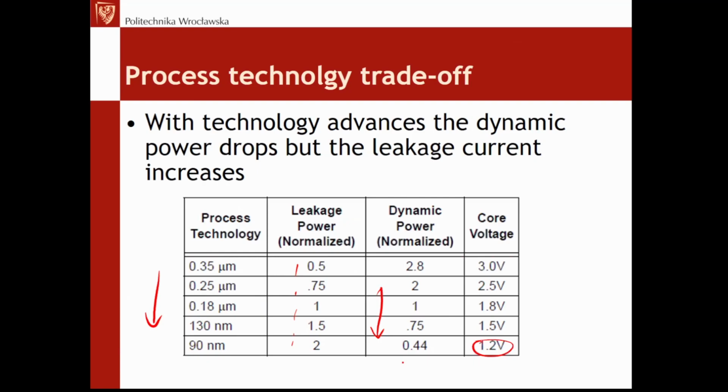Anyway, this chart, this table, is showing that it's not all that rosy to have the technology node reduced, and in some cases it's better to use in a design a device produced in an older technology node, because it will have lower leakage power, but that's only for very low power devices normally, because the dynamic power consumption definitely dominates the total budget.